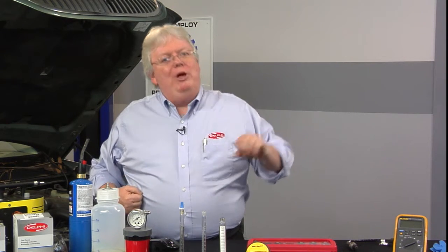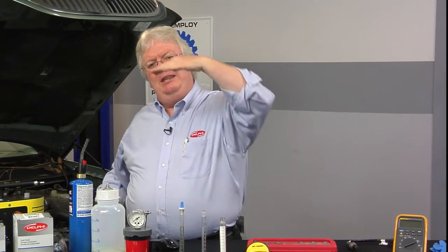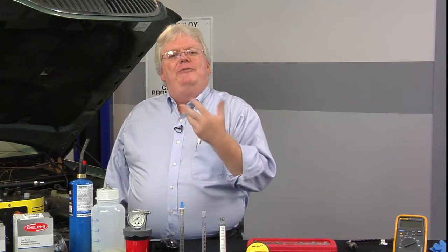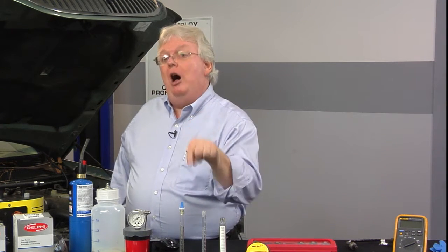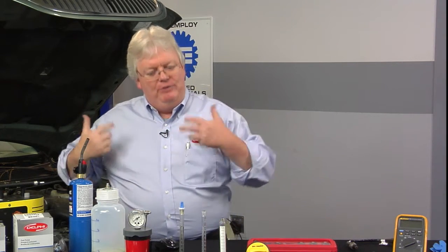Conversely, if you have fuel trim numbers that are normal at idle, but when you get on a road test they start falling apart and the numbers keep tracking up, or adding fuel, it could be a fuel delivery issue. The fuel pump puts out good pressure at idle in the shop. You get out on the highway and the fuel pressure drops, but mainly the fuel volume drops. It can't put out the volume. Therefore, when you've got good trim numbers at idle, but profoundly positive numbers as you go up higher into engine load values while you're road testing the vehicle, you probably have a fuel delivery issue.